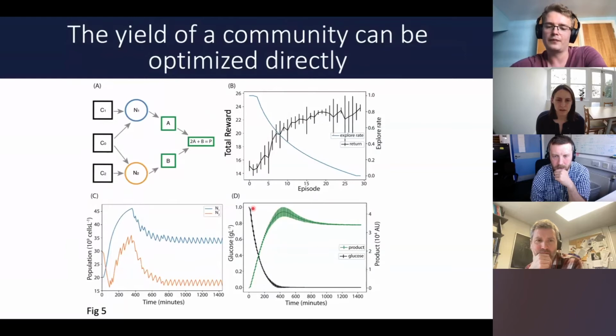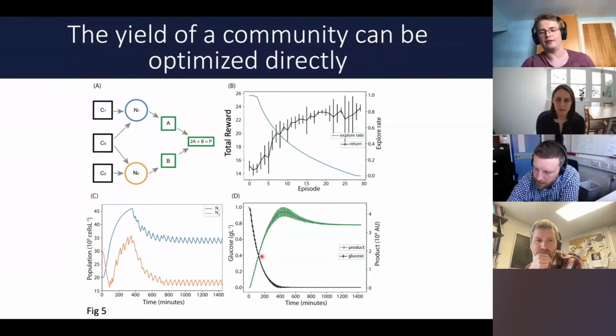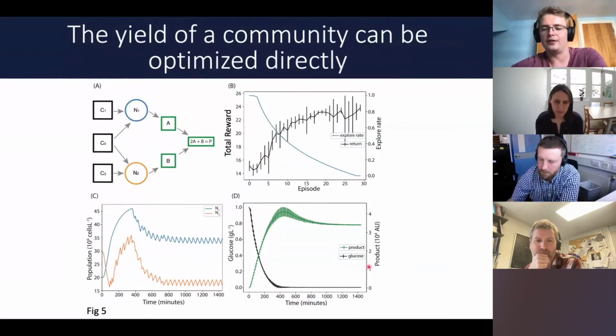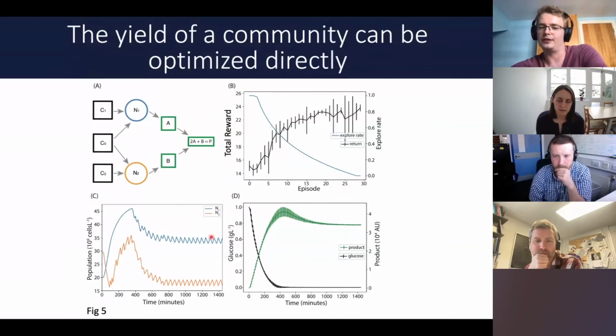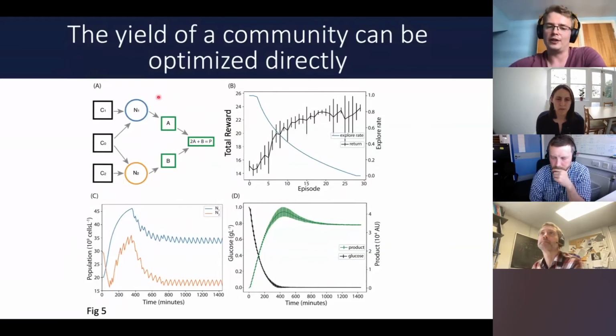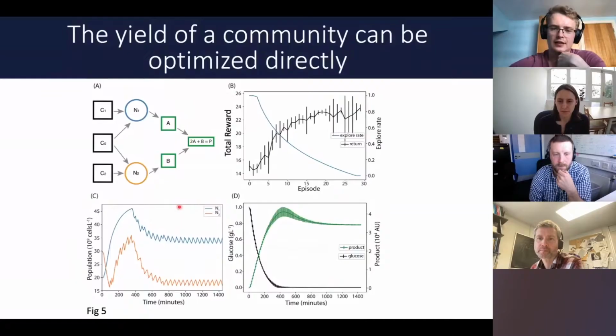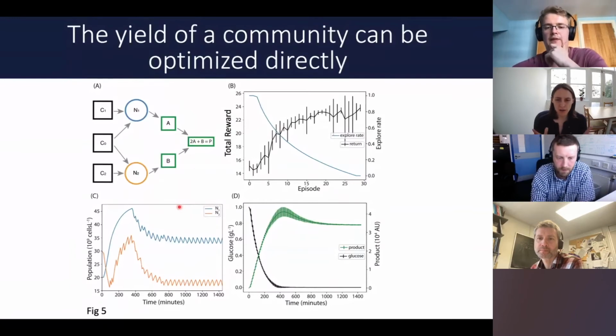And this is the level of carbon across our 24 hours for 10 repeats. And we can see that we're using all of our carbon. So this is good. It shows that just by observing this product output, we can drive the system towards the optimal state for maximizing the product output, if that makes sense. And we don't need to have any knowledge of how this all works, which is an advantage of model-free. In the paper, you talk a bunch about this concept of the inter-sample period.